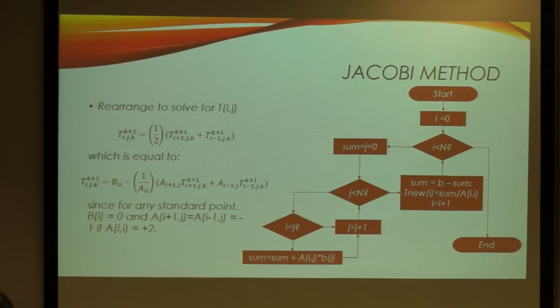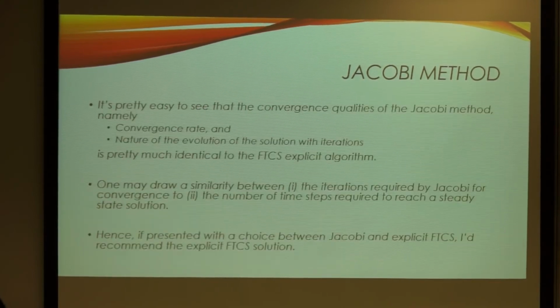So you take your finite differences using FTCS, but FTCS doesn't mean anything because it's steady. So just central differences, and you solve for T of K plus 1. You'll find that the temperature at K plus 1 can be computed in terms of the other temperatures, just like that. These two equations are the same. So it's no surprise that Jacobi works, because the computation can be related back to your finite difference representation. So it's very physical. They mean the same thing.